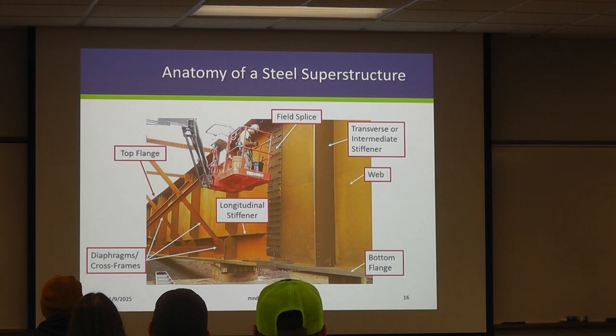Pieces can only be shipped from the fabrication plants at a certain length, right, because of trucking limitations. So we have to have a way to bring these pieces together. And oftentimes we'll do that with a bolted field splice. And we'll talk about that more.